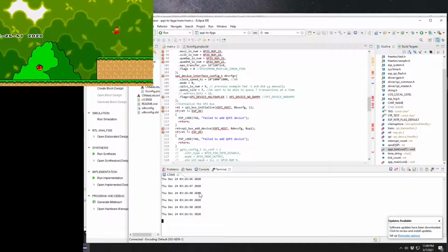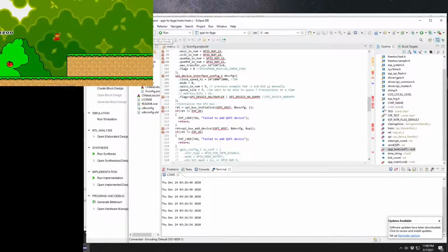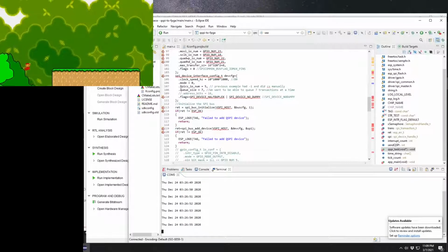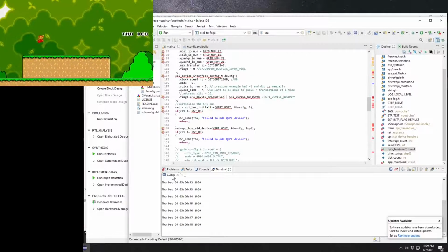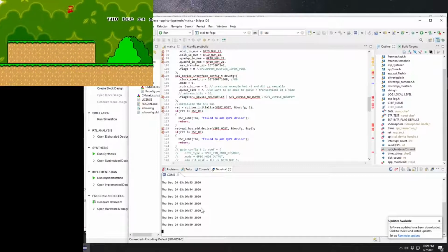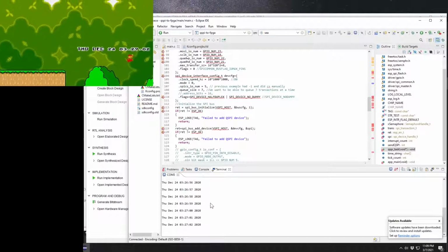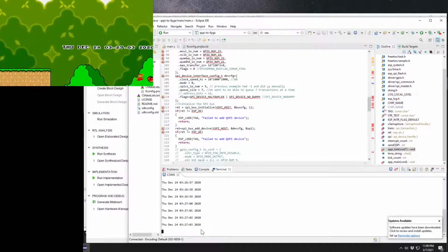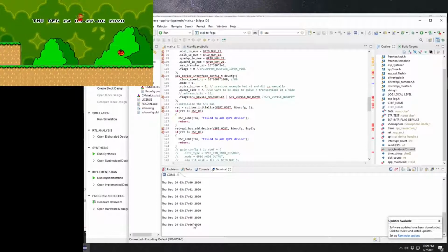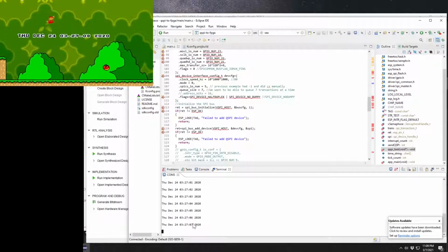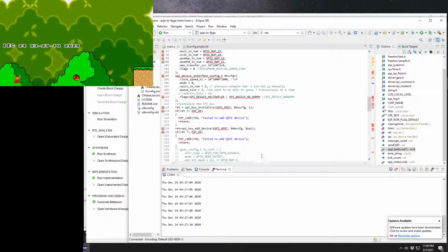Compared to using the command line, if I want to send a new build of the software to the ESP32, Eclipse knows that it should pause the serial console while it writes over the data, and then it reruns the serial console again. So I don't have to deal with the contention of remembering to turn it off and on every time I want to send new software over to the ESP32. So for development purposes, this is much, much easier.